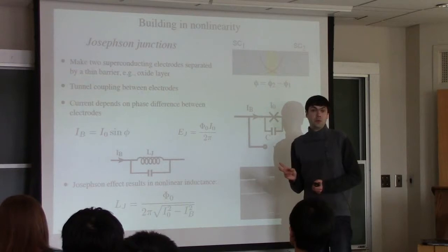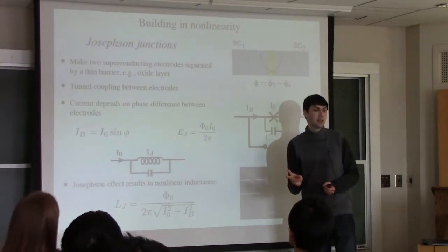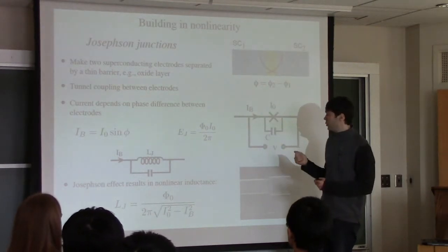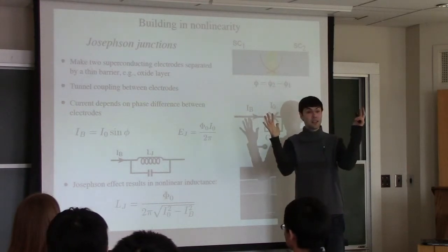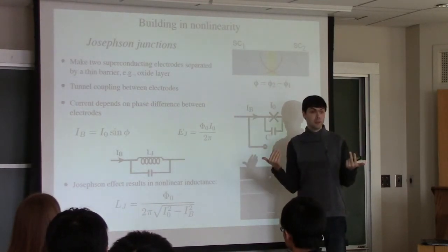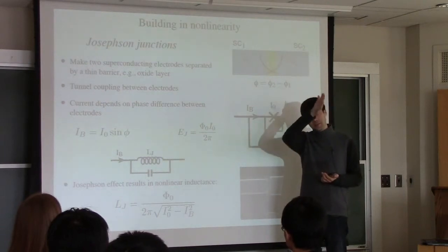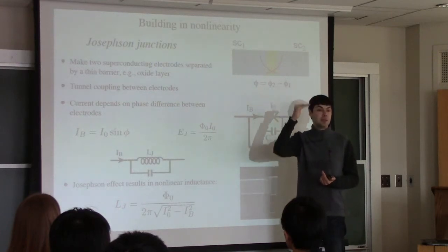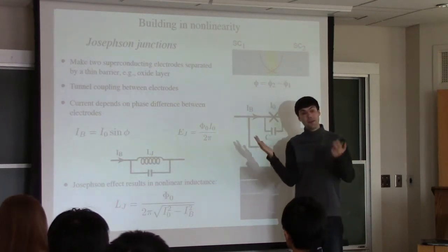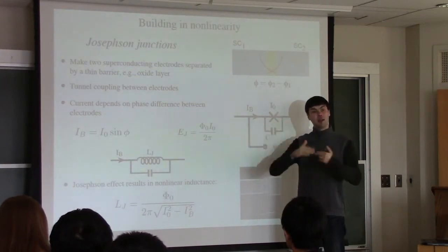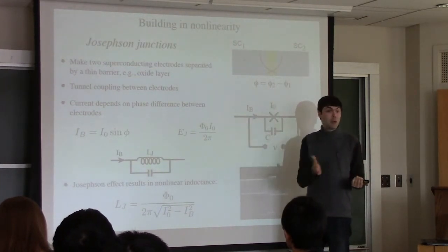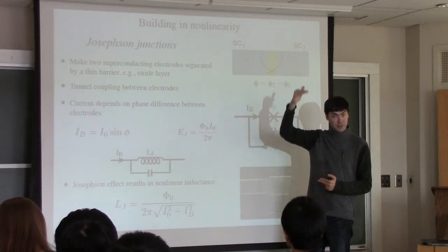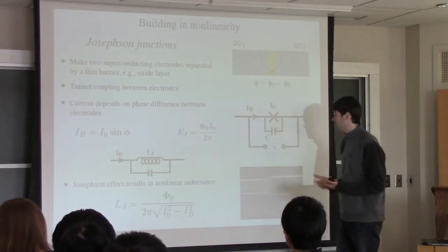In order to make a qubit out of a superconducting circuit, you have to make the energy level distances unequal. And that you can do if your oscillator is not harmonic but is anharmonic. So if the bottom of the potential is a parabola, all the levels will be equidistantly spaced. That is the case in an LC circuit. But if the potential is some other function, the energy level spectrum will be different. For example, a square well potential would give you, like in a particle in a box problem, right? The different level spacings. So that's one example.